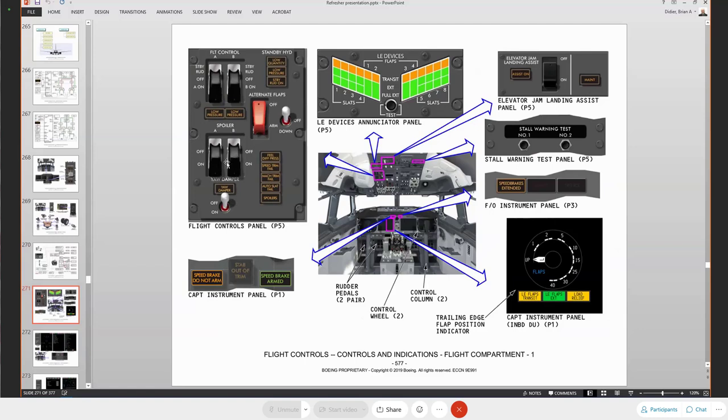The flight spoiler switches, the hydraulic switches, are typically used for maintenance. This switch also has an input into the spoiler control electronics, and really it's just a status message. It's telling the SCE that we either have the switches turned on or turned off. That's essentially all it is.